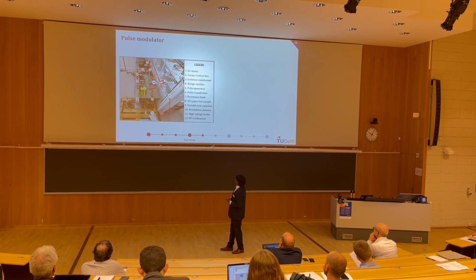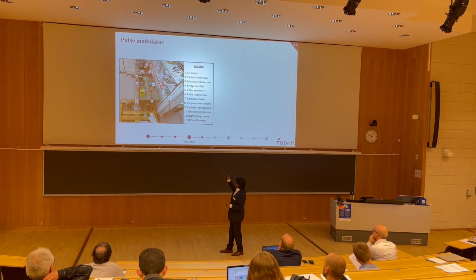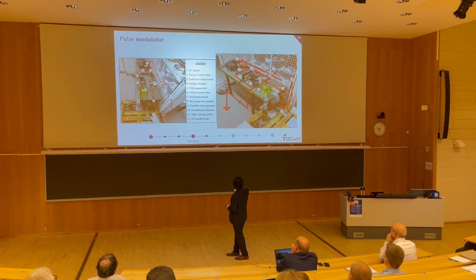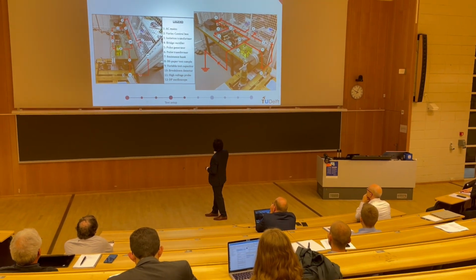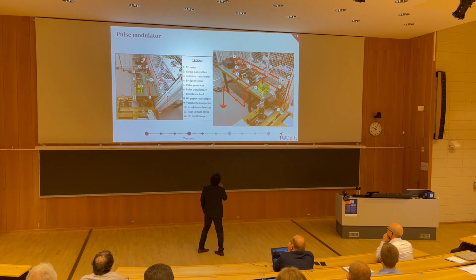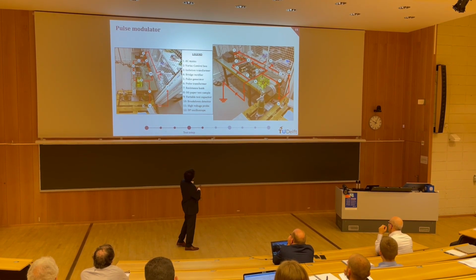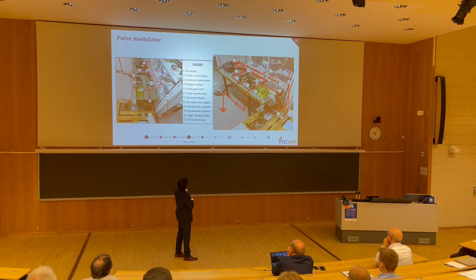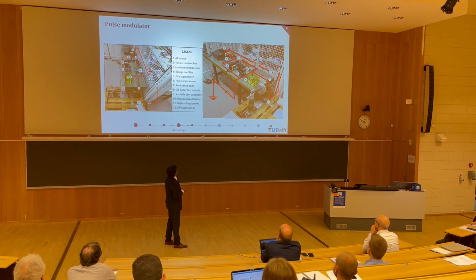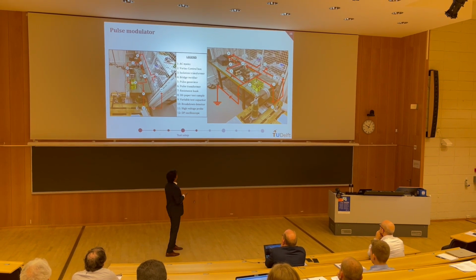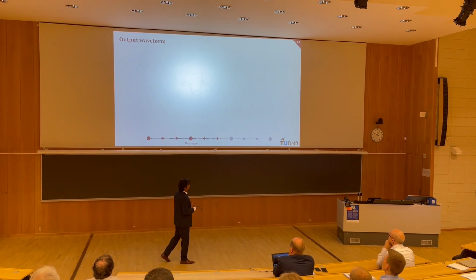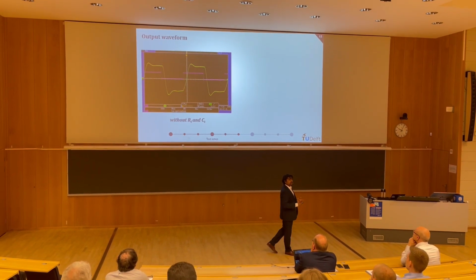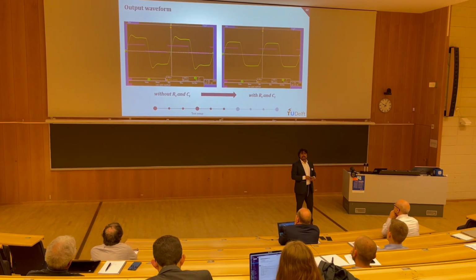The final setup looked something like this. You can follow the red line. It goes from here, goes all the way around, gets stepped up by the transformer. This is the resistor bank. This is the high voltage capacitor, and finally we have the oil sample, and an oscilloscope here to see the output waveform. We had something like this, but then with the test elements, we were able to make it something pretty like this.